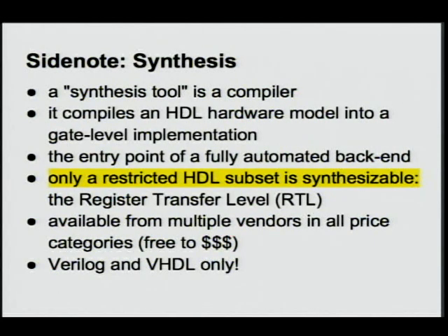Now, synthesis, unfortunately, is rather restricted in the sense that you have to write your HDL in a very specific way to get it through the synthesizer. Fairly low level, actually. I wouldn't say that it's like assembler, but it's fairly low level. And that level is in fact called the register transfer level. So when a hardware designer tells you that this model is at the RTL level, what this means is that this model is intended to be synthesized, to go to hardware directly.